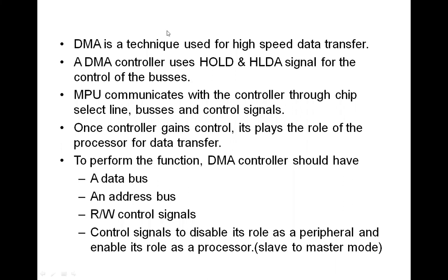Now, what is the purpose of the HOLD signal and the HLDA signal? HOLD is an active high signal and HLDA is an acknowledge signal. Now, what is the HOLD signal? The HOLD signal is an active high input signal to the microprocessor 8085 from another master, another input output device or controller, requesting the use of the address and the data bus. After receiving the hold request, the microprocessor unit relinquishes control of the buses in the next machine cycle. Whatever it is doing, it will complete its operation and then relinquish the control of the buses.